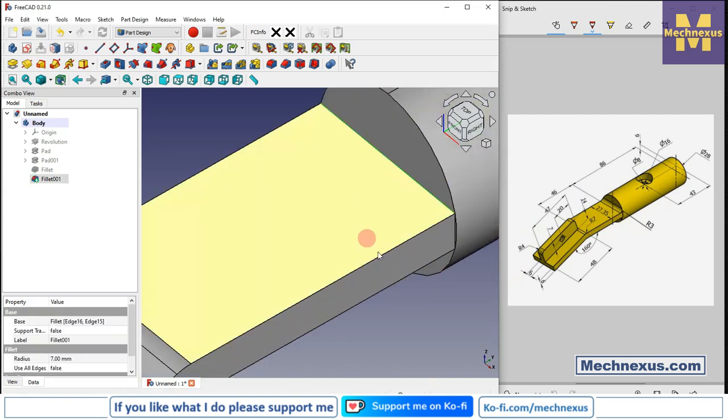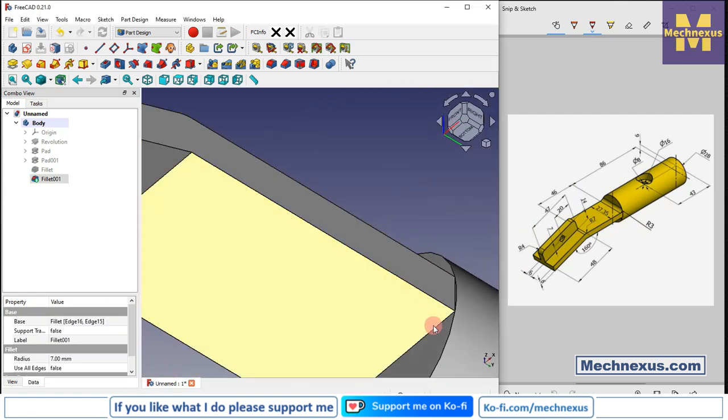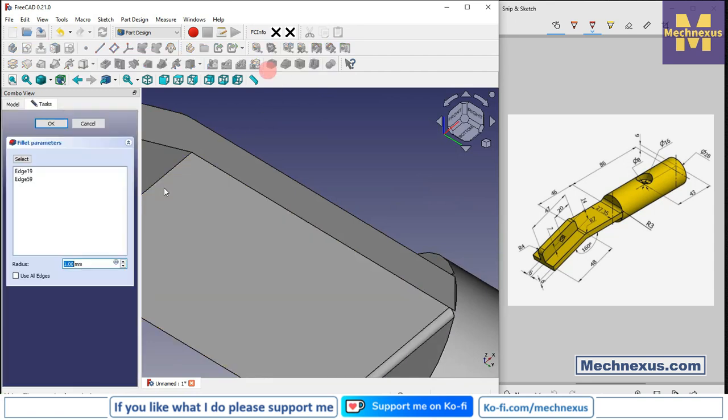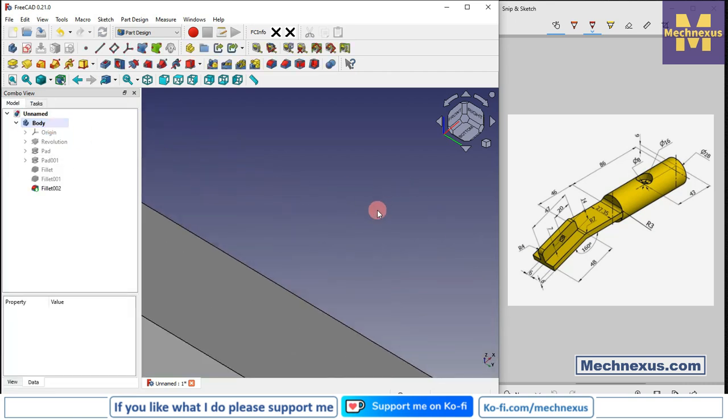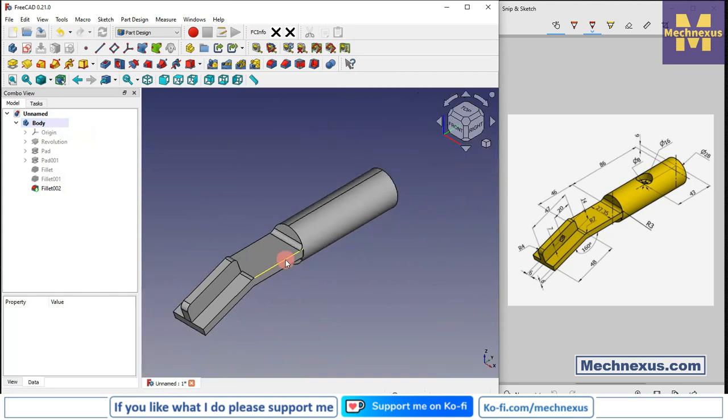So select this edge and press Control key and select this bottom edge and click on the fillet and provide the value of 3 mm. Now press 0 for isometric view.